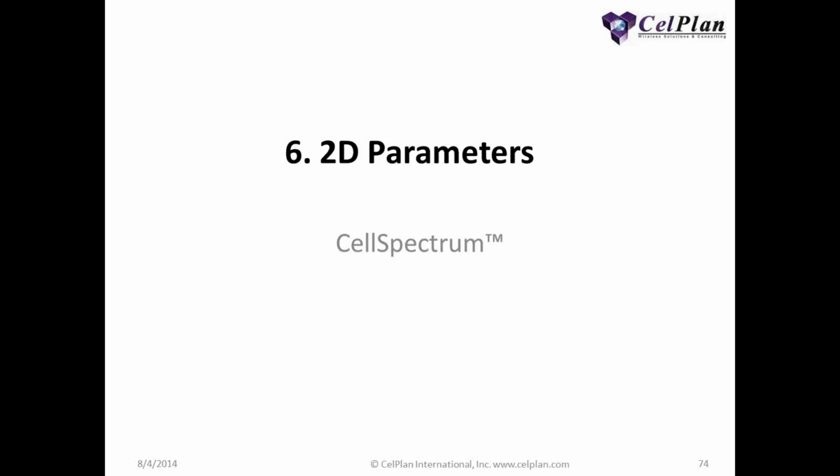And of course it was only interfering when the phone was being used. So we had a large difficulty of pinpointing, you know, and interference was coming from everywhere. So each time we go there to measure, there is no interference. And with this, as soon as the interference arrives, we can capture it remotely, capture the spectrum and then use this as evidence.